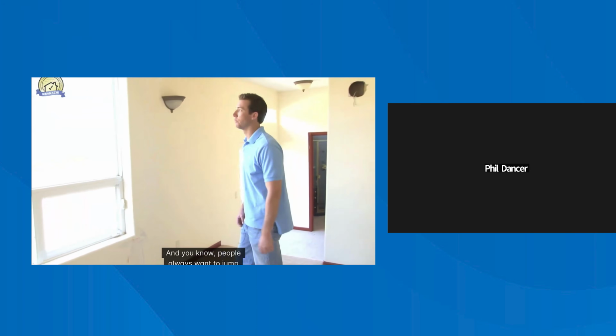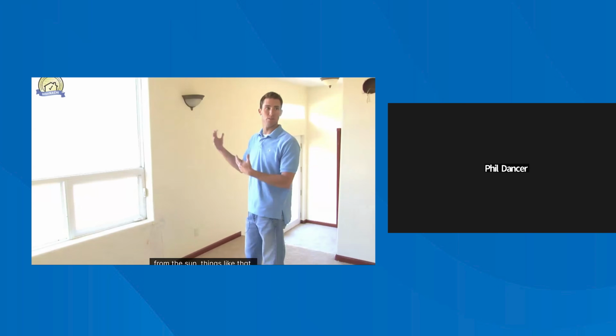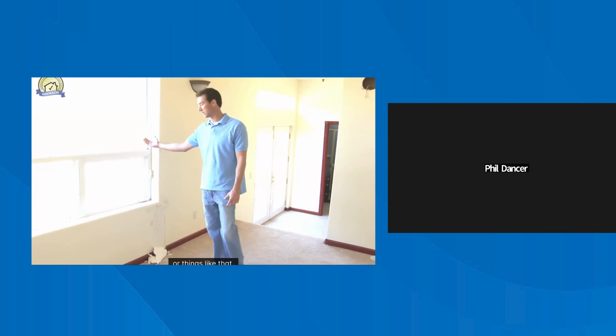And you know, people always want to jump to the conclusion that the window is probably warped from the sun, things like that. People always say, well, we just need a new window. But it shouldn't be ignored that as you get this vertical foundation movement, you're going to get separation from the window, and it's not necessarily your window warping or things like that.